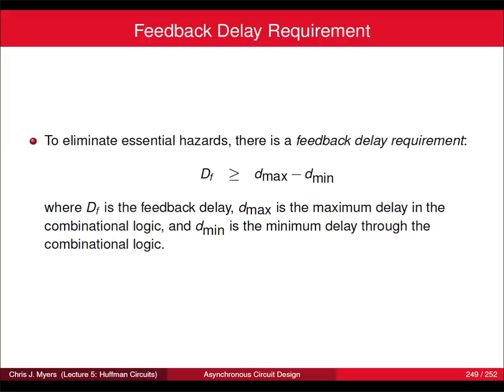So you have your next state logic output coming around to become your input. Mm-hmm. So you would have to add a chain of inverters, which has a minimum delay greater than this difference in delay. But there's no specific value. It's just an ideal quantified value, where relatively one is bigger than the other.